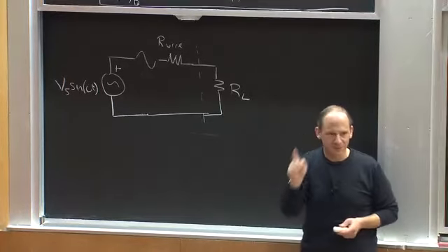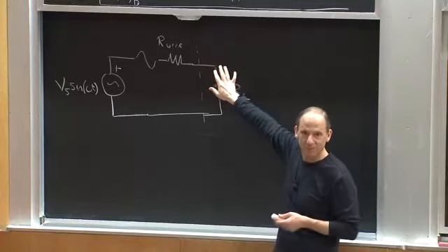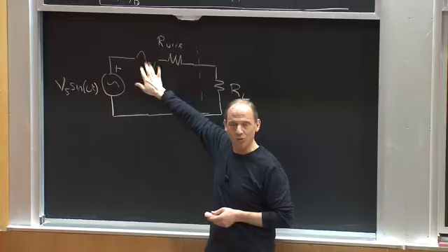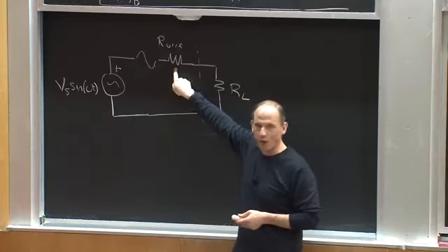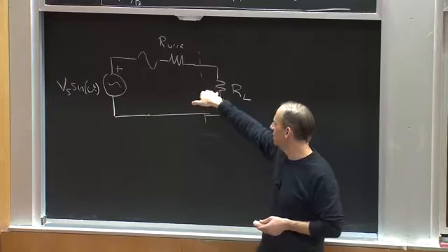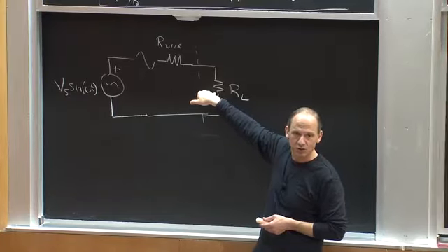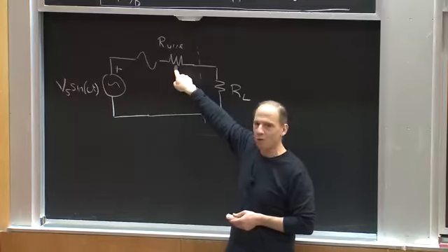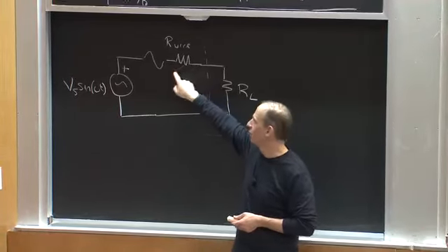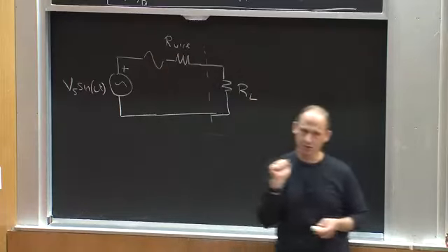What the breaker is specifically designed to do, I mean, if it's the fuse in the equipment, maybe it's trying to help you prevent the equipment from burning down. But the breaker back in your home or in the wall is designed to protect the wiring, right? Because you could, in principle, plug something in that would be happy enough, wouldn't die, but would draw too much current. And then what happens when your wall wires overheat? They start a fire, and then really bad things happen, right? So the fuse, the breaker, is really designed to make sure that the wiring doesn't overheat.